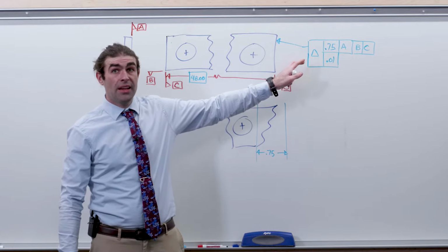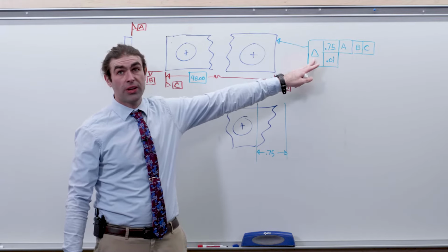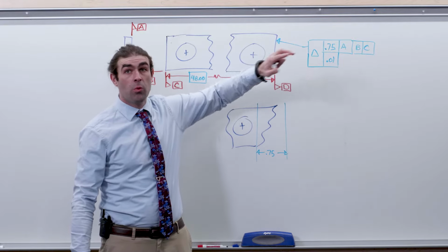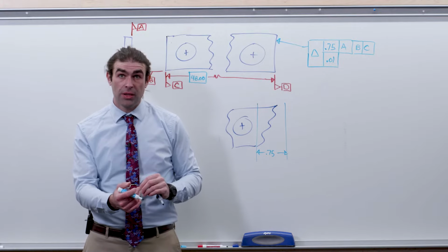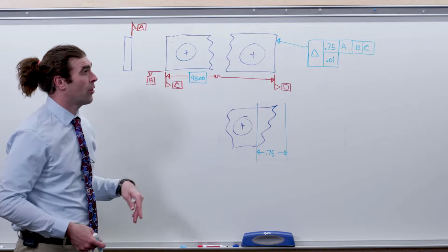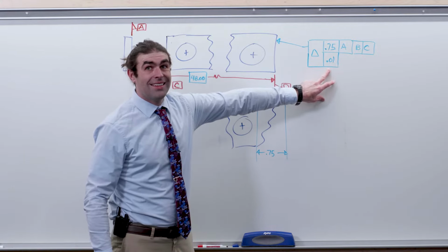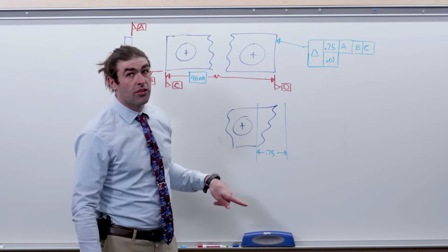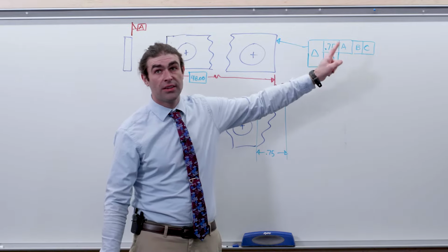What I've done is made this a composite profile, so one geometric characteristic symbol with more than one segment. Now, in this particular example, two single segments means the same thing, but I'll make it composite just to show you the one symbol. Okay, so this 10 thousandths indicates that this surface needs to be flat within 10 thousandths, and it also has to adhere to this upper segment.